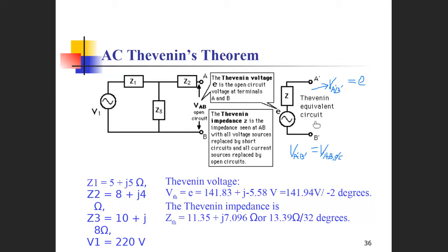for the right side, in these figures you can see that the internal electromotive force E is equal to the terminal voltage V A prime B prime when it is open, because when it is open, the current will be 0 between A prime and B prime. Then there is no voltage drop across the Z. Therefore, the terminal voltage equals the internal voltage because the current will be 0.